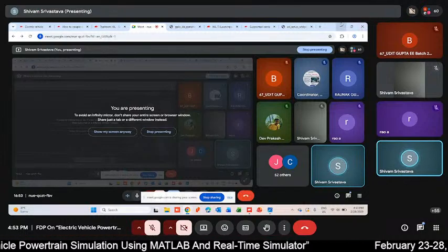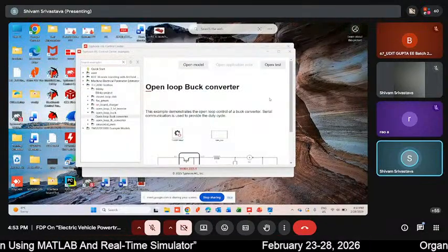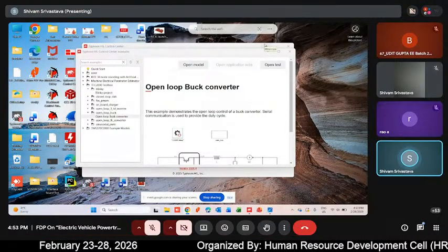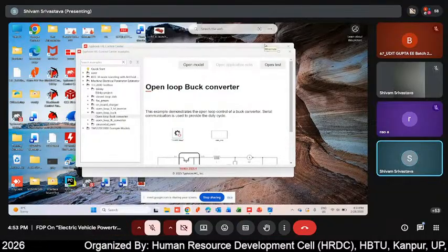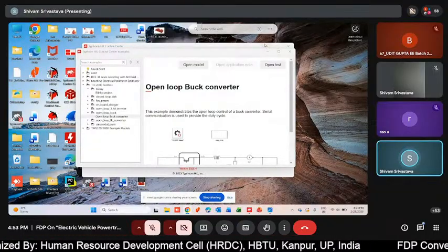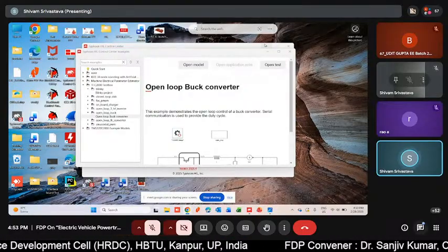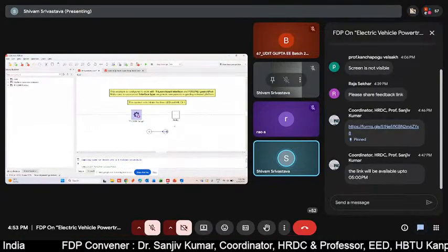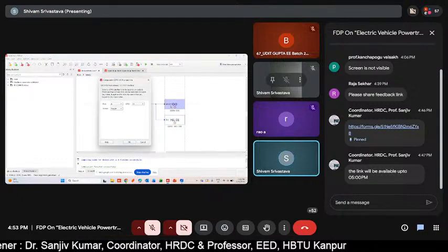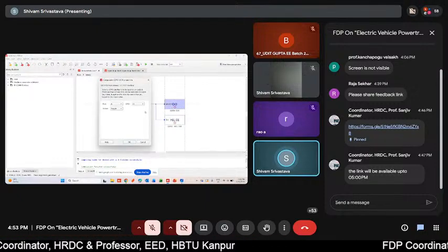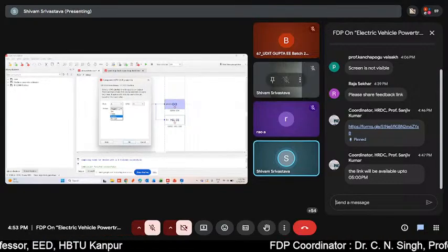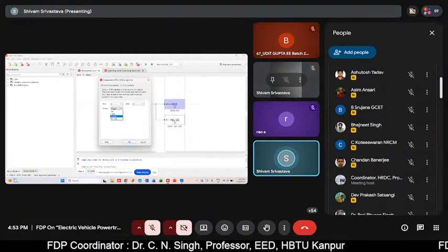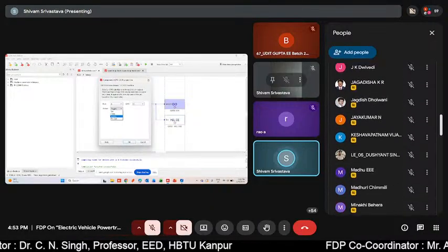So after this, what else can we learn from this exercise today is what other things we can do with this TI based controller card we have. You can go for exercises like what happens if you change the pin number associated with the GPIO pins, and how you can change the port level, or what happens if you change the action from toggle to set, or to clear pin, or control pin. Such kinds of scenarios you can use.